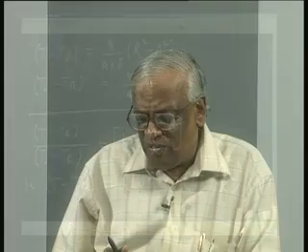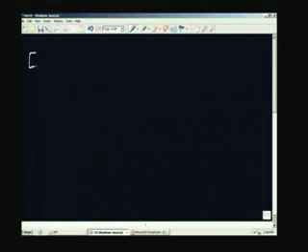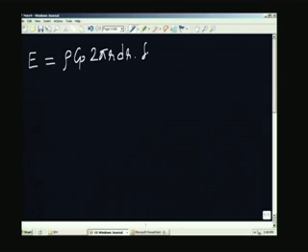So, if I want to find out what is the energy contained within the foil, I have to find out the following. The energy contained in the foil is nothing but density times the specific heat times the volume of the element. The volume element is 2 pi r dr multiplied by delta, this is for an element, multiplied by T minus Tr.